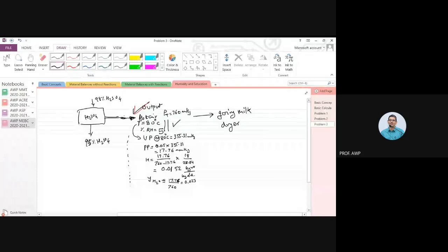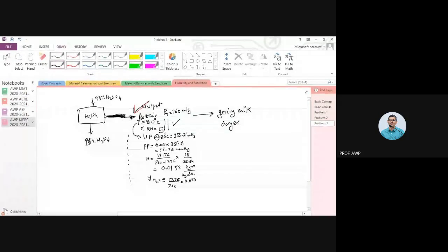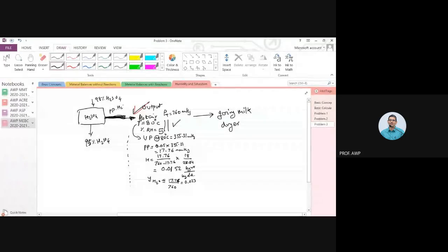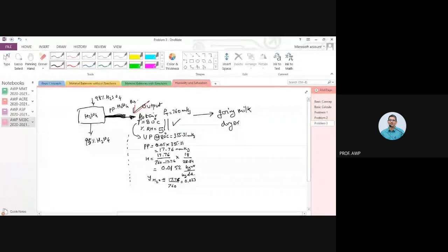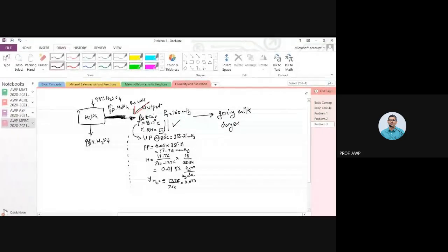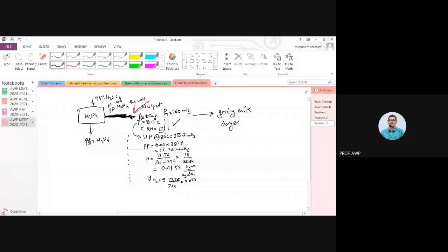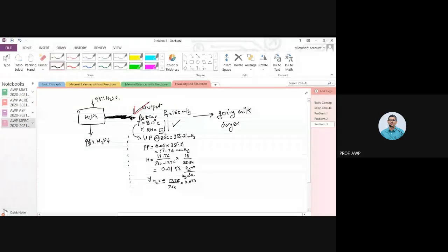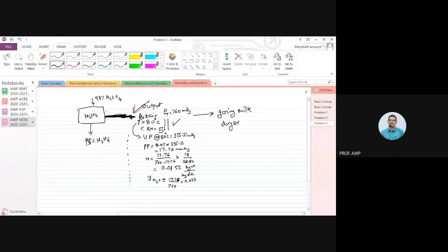this air that is going out will be saturated. Well, I should not say saturated. This outgoing air, okay, we can say saturated, because this outgoing air will have some partial pressure of H2SO4 as well. It will have partial pressure of water vapor. This air will contain water vapor because some of it has been condensed, has been absorbed by H2SO4. But because H2SO4 is liquid and air is coming in contact with that, it will be saturated with H2SO4 vapors.